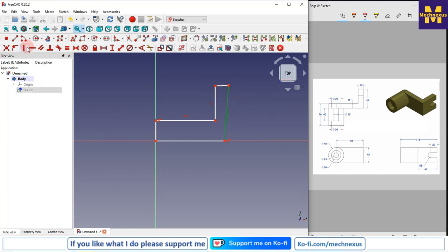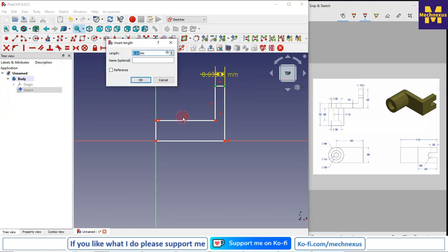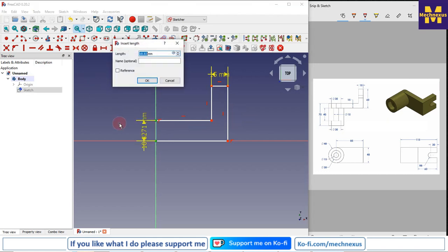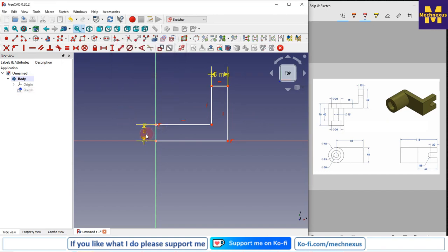Now I will give this vertical constraint, and the thickness is given 15. So select this point and this point, dimension 15, this one and this one 15, and now this dimension is also very important.